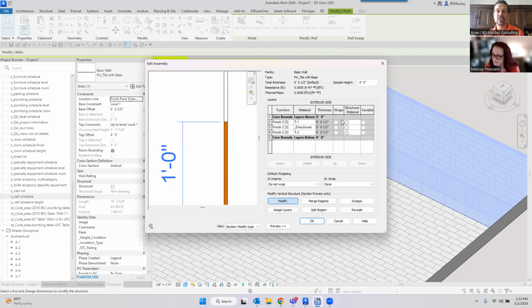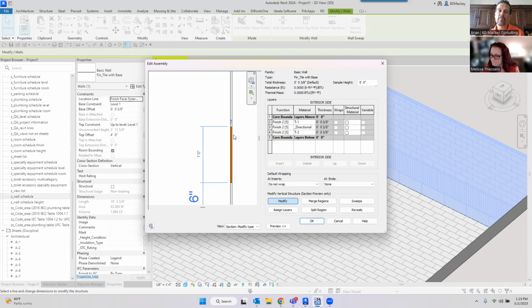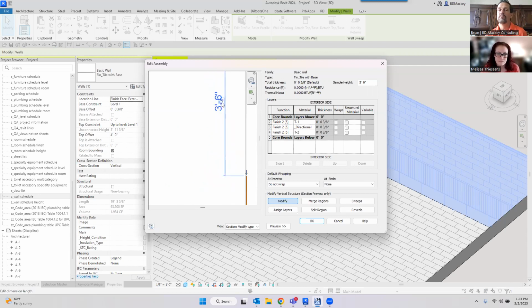And that is how you change the thickness of all of them. If you are trying to change the thickness of all these, you grab the modify, grab any of the back lines, change that thickness to be whatever you want it to be, and you can start going through and playing with it. You'll also see that if you grab the modify on one of the horizontal split lines, you get a little arrow. That little arrow says, where's that dimension coming from? This dimension is coming from the bottom and going up. If I click the little arrow, I can make that dimension always be 3'6" from the top. Or if I wanted to change that value and say, no, always be 2 feet from the top, now I can go through and start setting that up.